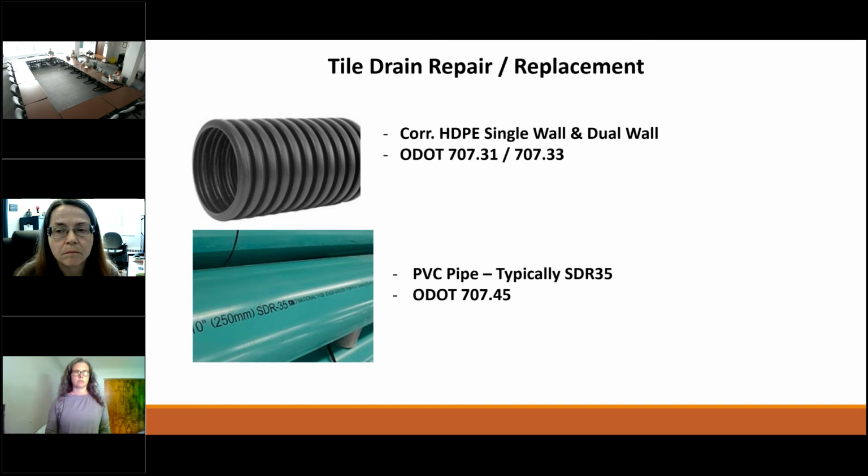The gaps in the pipe will allow soil to be, in a sense, sucked into the pipe, which creates an opportunity for a sinkhole, or for silt to get into the stream, and you have silt on the downstream flow. In some cases, you can actually just fill the pipe with the soil that would be around the pipe, or the stone as well, and plug up the pipe and back up your ditch from there.